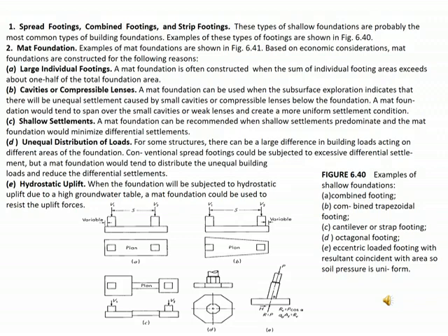Firstly, if we have to utilize less individual footings, we utilize a mat foundation. A mat foundation is often constructed when the sum of the individual footing areas exceeds one half of the foundation area.